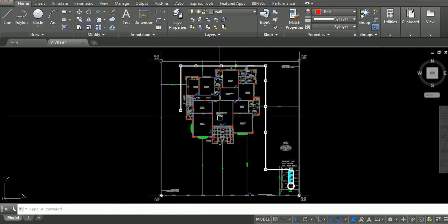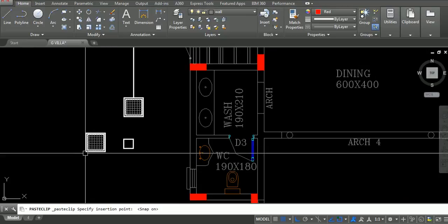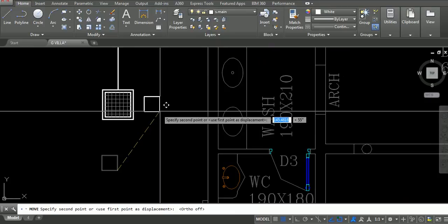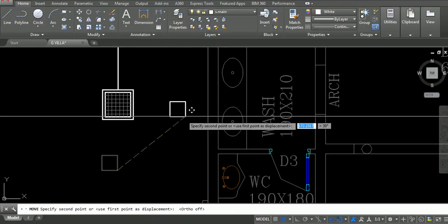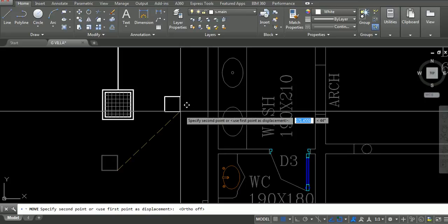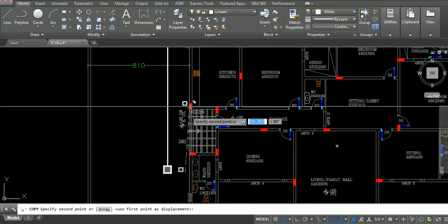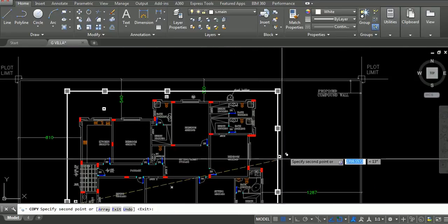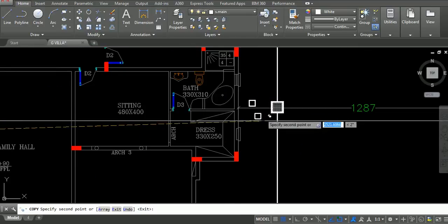Okay, the next step will be adding gully traps. I need to add gully traps also. I'm going to explain later more about gully traps and why they are needed. But here I'm just going to explain where they go. I'm going to put one near every bathroom or kitchen. One here, one here, one here, one here, and one here.